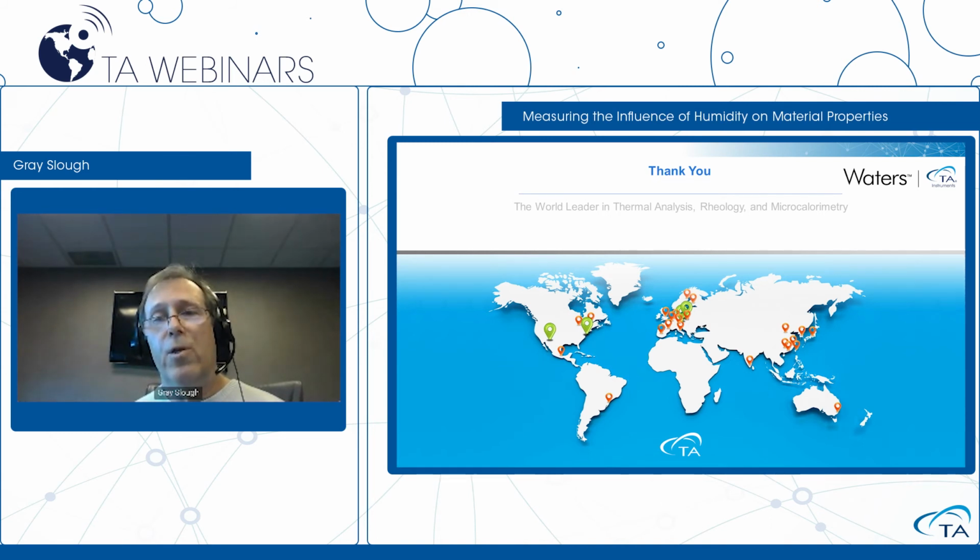On the TMA RH, again, the temperature and RH signals are calibrated in-house. But when you get the instrument, you would be calibrating the force. Anybody familiar with a TMA knows that you calibrate the application of force on that instrument. There is what's called a probe calibration, which is used to measure a number of things on the probe, including its weight and its flexibility. You would also calibrate a cell constant for that instrument, which is useful in making sure that CTE values that you measure are calibrated with respect to, say, an aluminum slug.